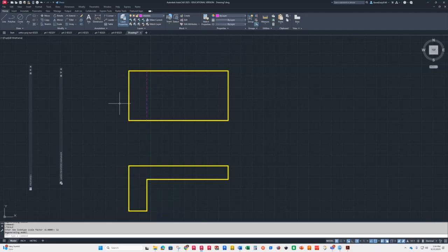Anyway, so we got our hidden line, we got it fixed. We did line type scale, we changed it to, like I said, I used 12. You can't see it on the screen there, but that's okay. You can at home, and you can later on when you watch the video. So there you go. All right, so I got that hidden line there, so that's cool.